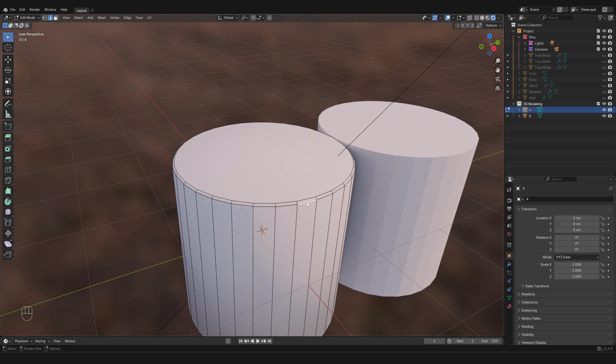Now, if I wanted to select the whole set of faces, I would make sure I am in number 3, face selection mode, and then I would press down Alt. And if I wanted the vertical section, I would double tap here. Whereas if I wanted the horizontal section, I would tap on this side. It doesn't have to be this specific edge or this one. Any will work. It's just that this side will trigger the horizontal selection and this the vertical, and you will get a sense for it immediately as soon as you start playing with it.